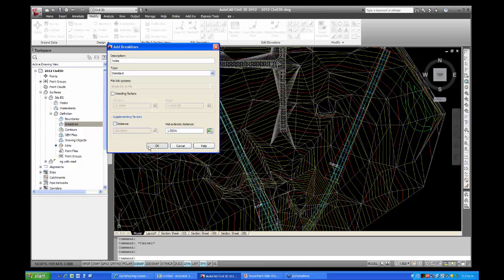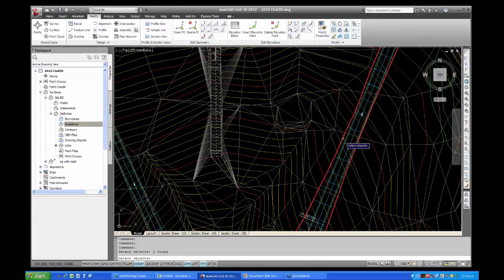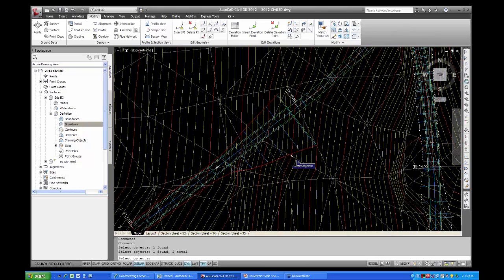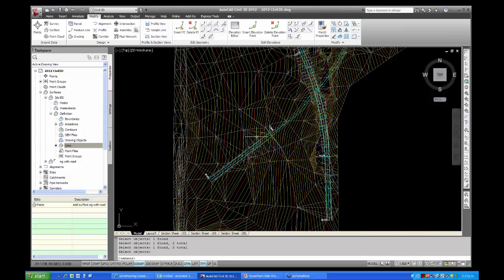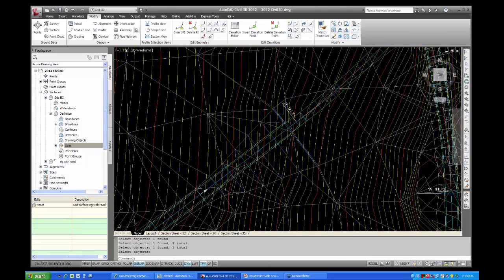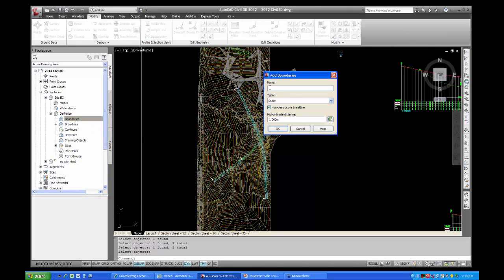Type of standard, it's all good. So I'm going to select that one, and we've got two more done the same way already over here. That one and this one for our abutments before the bridge. If you watch the triangulation in the background, you see it's exactly matching the triangulation of the edges of the corridor now. Then simply apply those as hide boundaries as well. Type as hide. Actually, it should be holes. Be better. It's going to be destructive. We go OK.